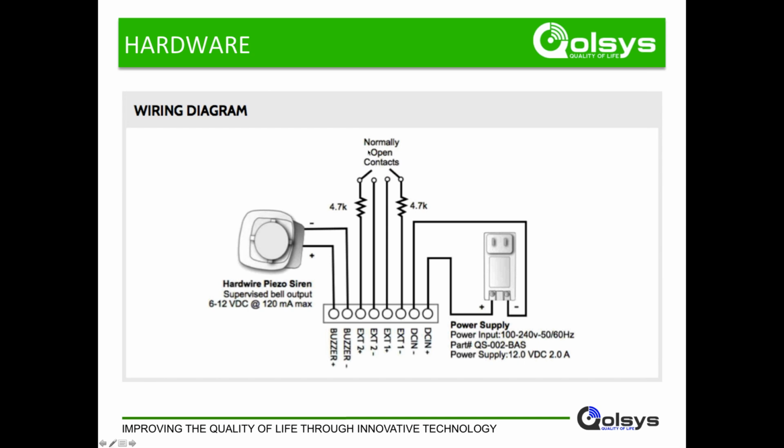The reason this says normally open contact is we actually follow the ESA definition of what's normally open, and if you look in your ESA dictionary, it says that a normally open contact, not a normally open loop, but a normally open contact is a contact that's open when no external force is applied, meaning when there's not a magnetic presence, the contact is open. And again, in our industry, almost everybody has cut over to the exact opposite. Everyone would call that normally closed. In actuality, we should be calling it a normally open contact and a closed loop circuit. But that's the reason for the formality there, so don't be confused by that.